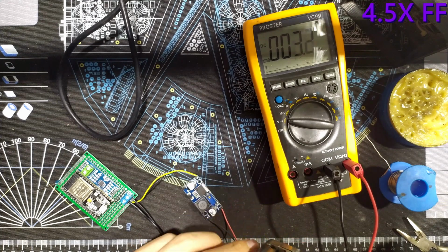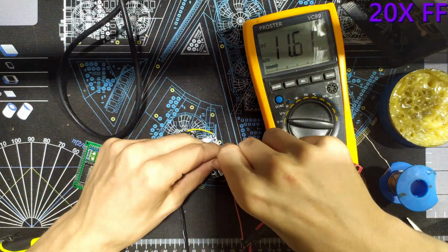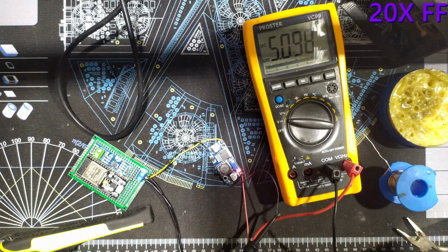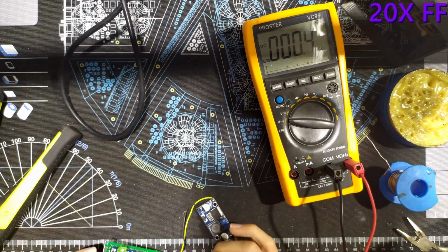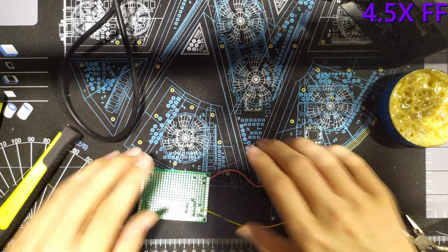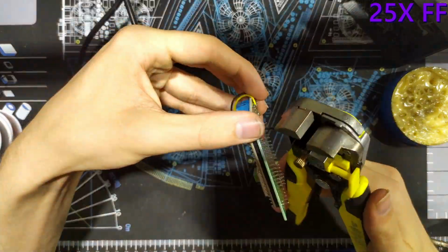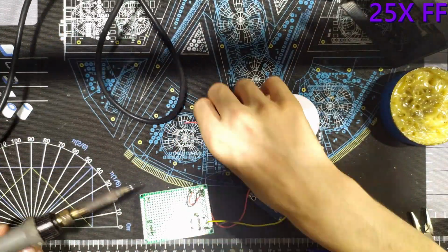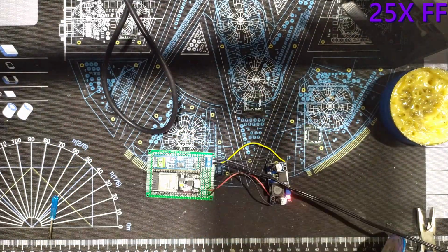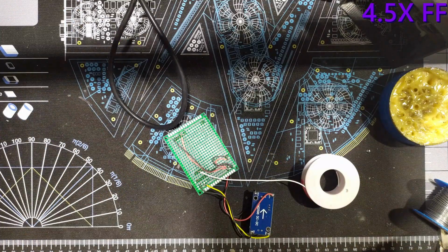I then used my multimeter to set the correct output voltage on the PCB by rotating the potentiometer with a little screwdriver. Yeah, that took a while until I got it right. After I got it tuned in, I soldered the 5 volt cable to the PCB and started connecting the ESP32 and the transceiver board to it. I then started wiring up the signal cables for the pin headers. That also took a while.